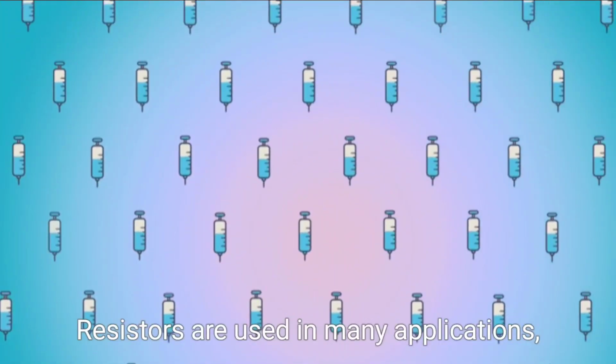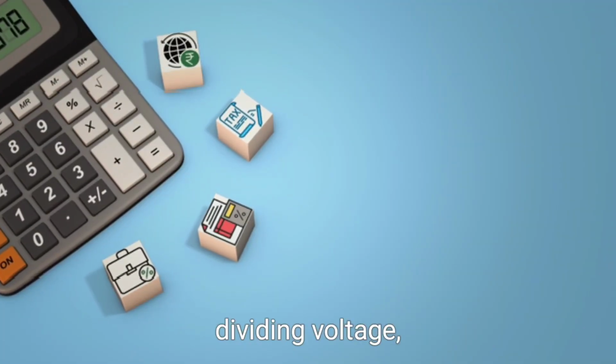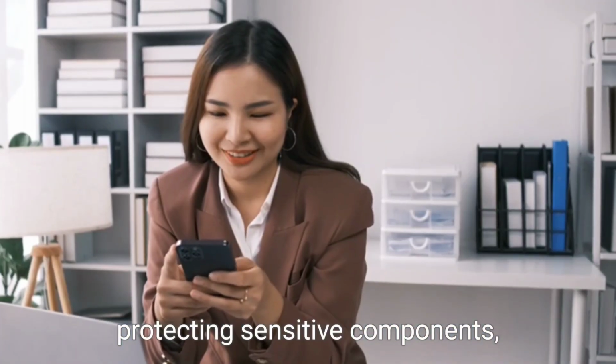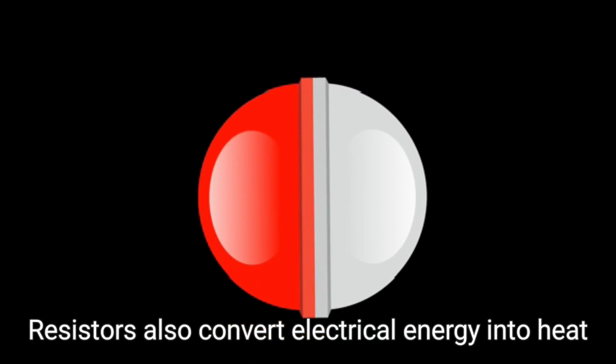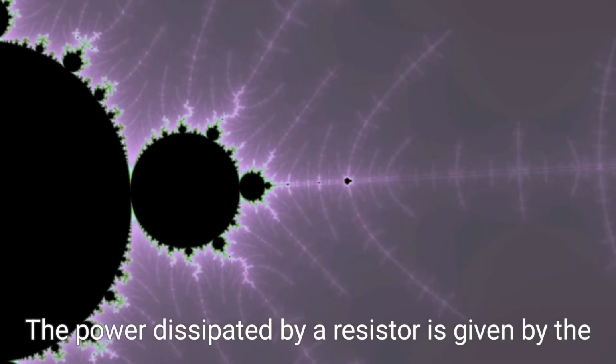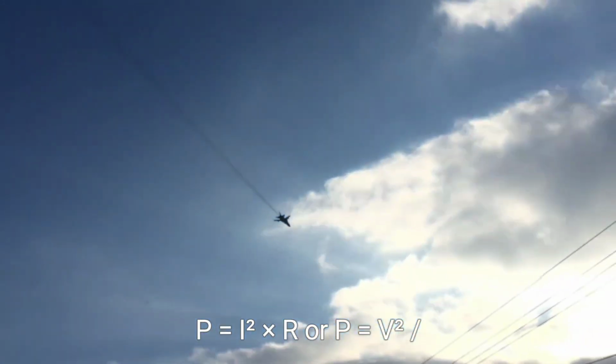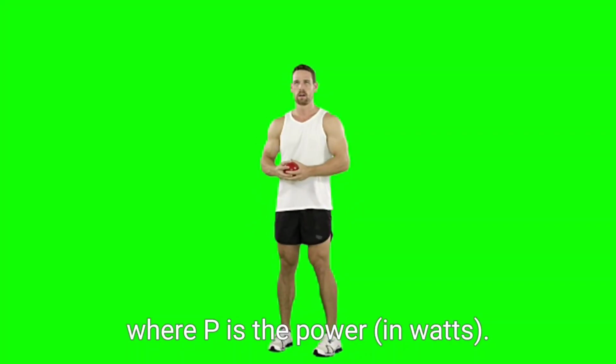Applications. Resistors are used in many applications, such as controlling current in a circuit, dividing voltage, protecting sensitive components, and shaping signals. Power dissipation. Resistors also convert electrical energy into heat as the current flows through them. The power dissipated by a resistor is given by the formula P = I² × R or P = V²/R, where P is the power in watts.